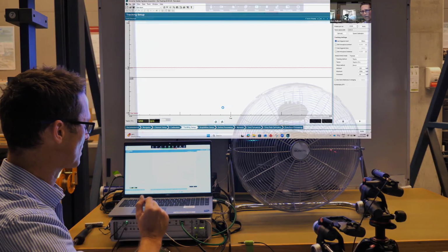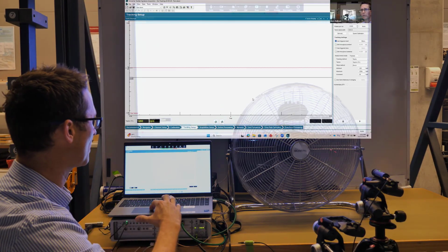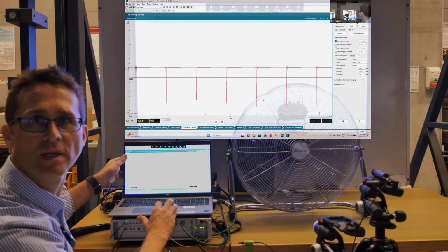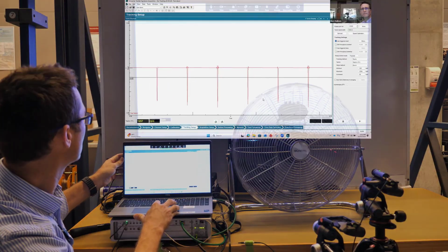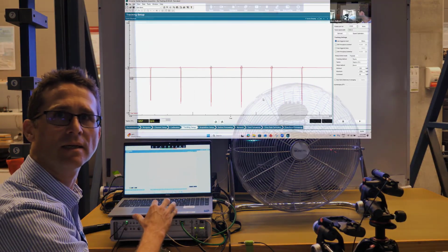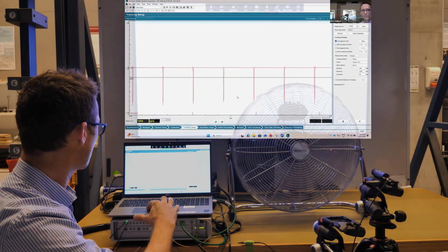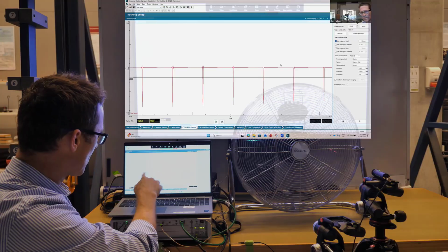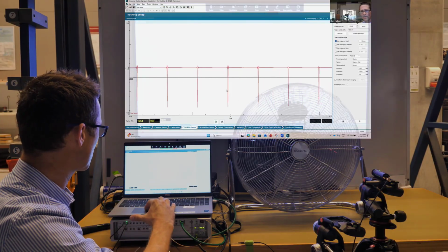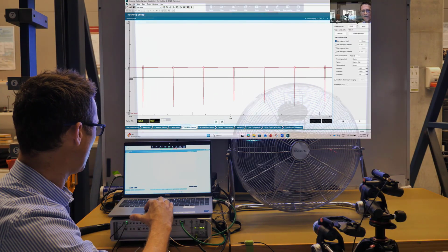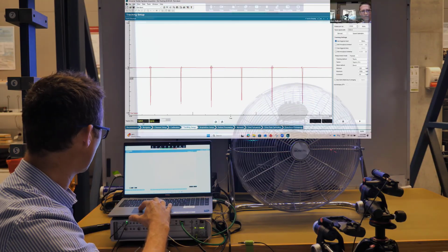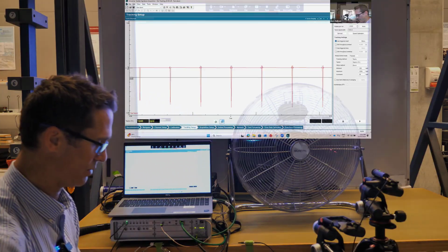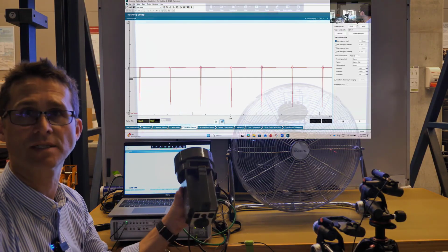It just takes a while to redefine the tacho bandwidth. So now there are some very nice pulses passing through in front of the display here, which hopefully, despite the intensity of the displays, is visible in the video recording. And so knowing the time between, or determining the time between those pulses, allows me to extract the RPM, which is about 1252.